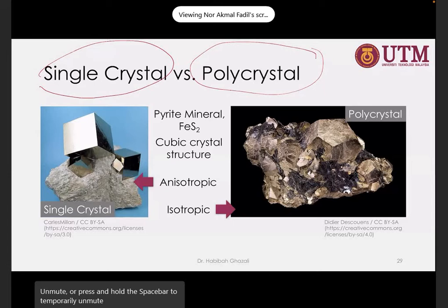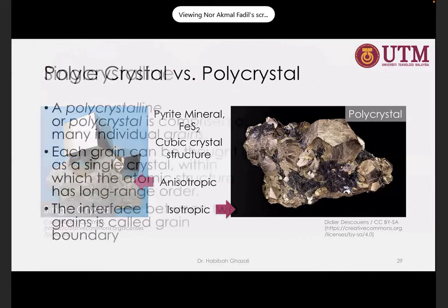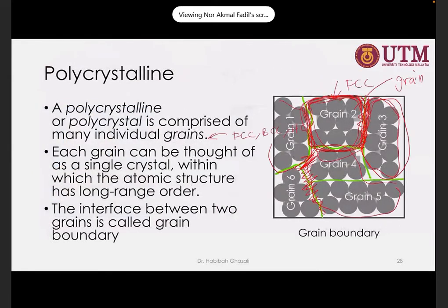Imagine these planes need to operate. The turbine operates for more than 9 hours, and the blades rotate and do the heavy work, and the temperature may reach up to 1000 degrees Celsius. So there is force subjected to these turbine blades rotating. Cyclic loading is very high on the blade, so they have to eliminate what? They eliminate the grain boundary because it is a weak point.